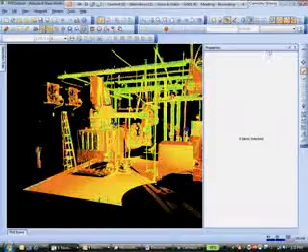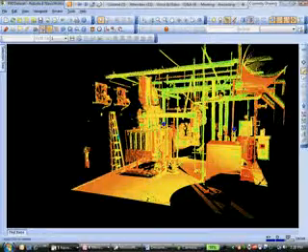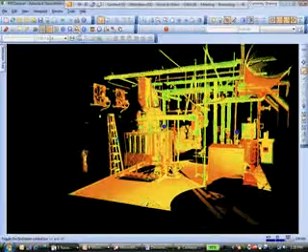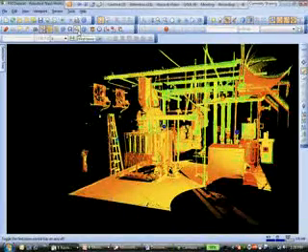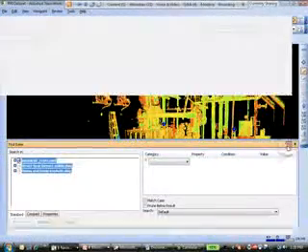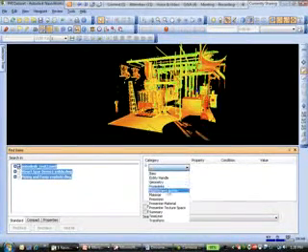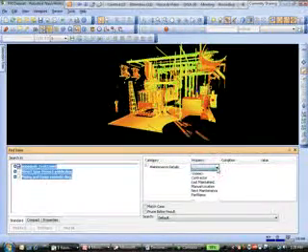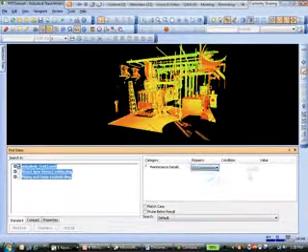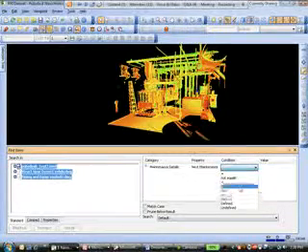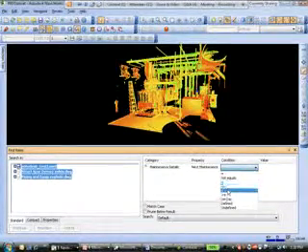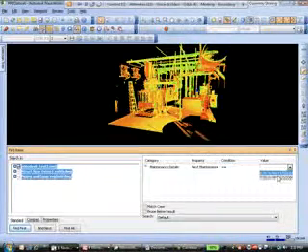Now where this becomes even more useful, if I minimize this, leveraging the Find Item tool, I can now search through the model and say find me all instances of a boiler that needs to be maintained within, let's say, 6 months. So bear in mind, when I was looking at the property information, that information from those databases carried over. Now in the Find Items, I can search out for maintenance details, and I can say I'm looking for the next maintenance, and then for condition it gives me a couple of options here. I can look for a specific date, or I can say greater than or less than, and then now it's showing me the different values that are on here.